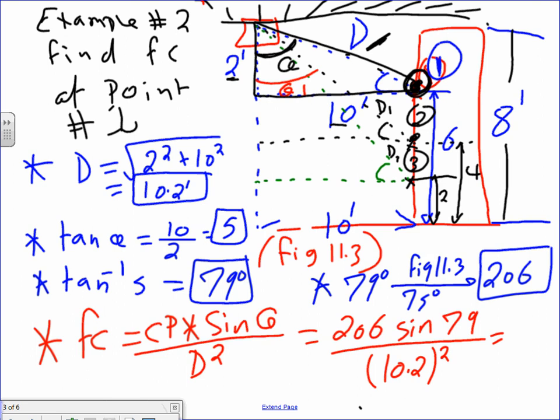And gentlemen, if you do the math, this should get you a healthy, wealthy number 2. 2-foot candle. That's what I give you on the test, guys. I give you a situation like this where you have to find the distance and you have to find the angle and then plug them into the formula. Would that be hard? Yes, no, vertical. We did vertical before. It's not nothing new. So that's what this test is all about, what this chapter is all about. Finding the candela power.